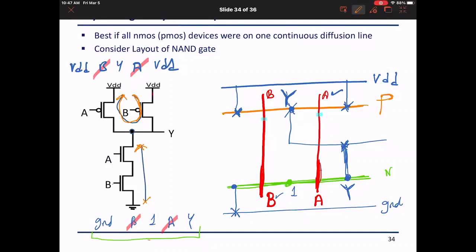Professor, systematically draw the track from VDD to ground in the PMOS and in the NMOS. Systematically, I divide the P network alone. I look at it alone. I try to find a path that is going to visit all the transistors only once. Okay, so this one starts from here and ends at A, right? I need to have a starting point, right? This is my starting point.